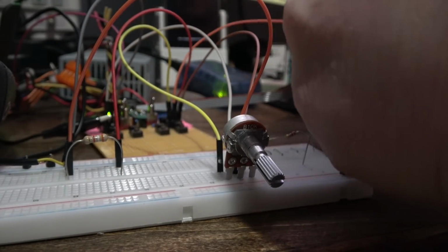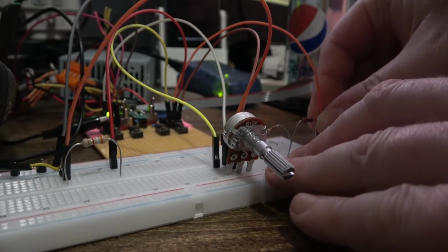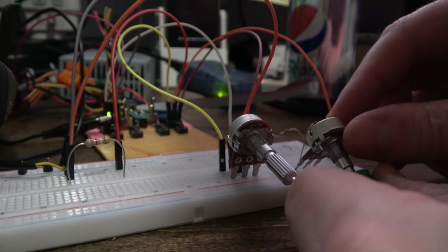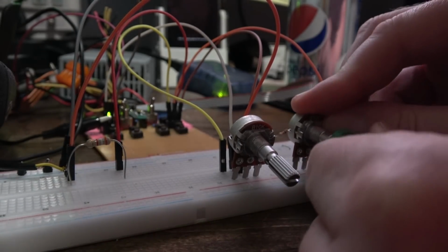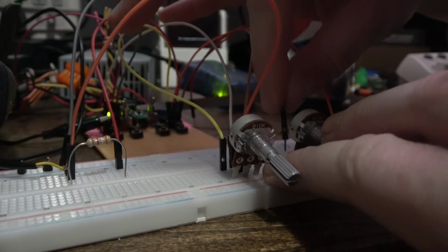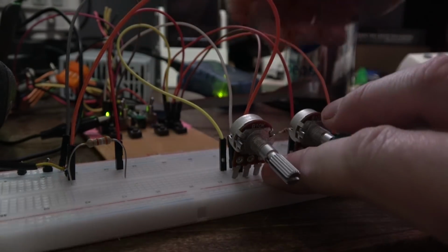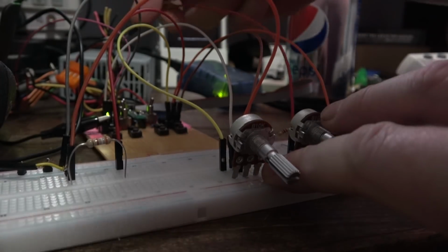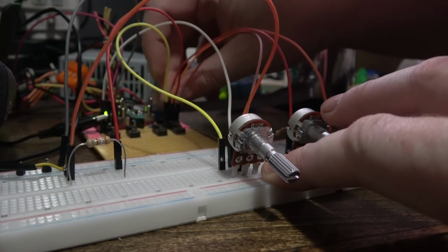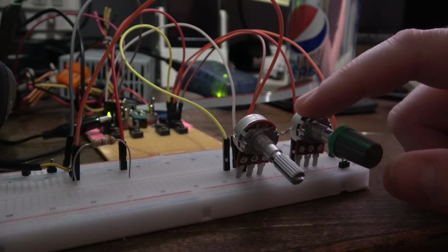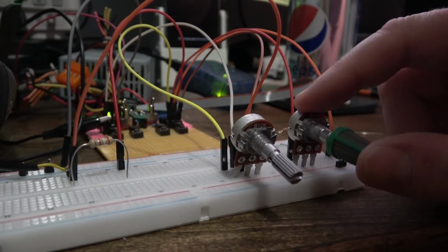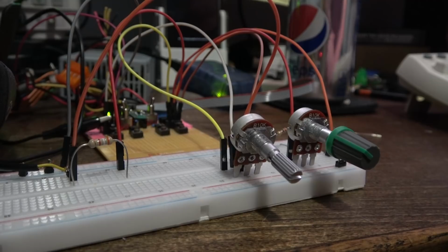Happy little clouds. There we go. The other side of that, I'm going to attach this potentiometer. I even put a little knob on it. How professional. The other side, or the wiper, of that we're going to attach to PB0, which is also reset. But again, with the high voltage programmer, we can use it. We just have to flip the toggle switch every time we program. And then I'll attach the other side of that to ground, and we should be able to use this as a potentiometer player control. Of course, we'll have to use the ADC, which we'll look at right now.